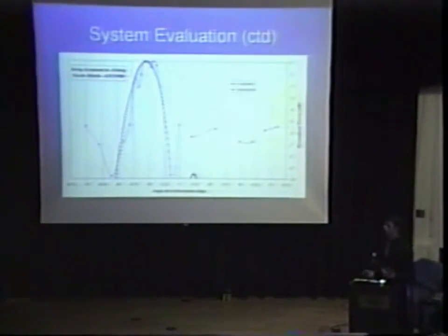I'm going to go through each one of the scan angles to show you how my results agreed with what was expected. This blue curve here is what HFSS had showed was supposed to be the appropriate beam. You can see that this is a scan angle of minus 25 degrees off of broadside. You can see that the beam agrees very well considering the test setup. Over here, you can see that there's some extra power being received, and that's just ambient power being received.